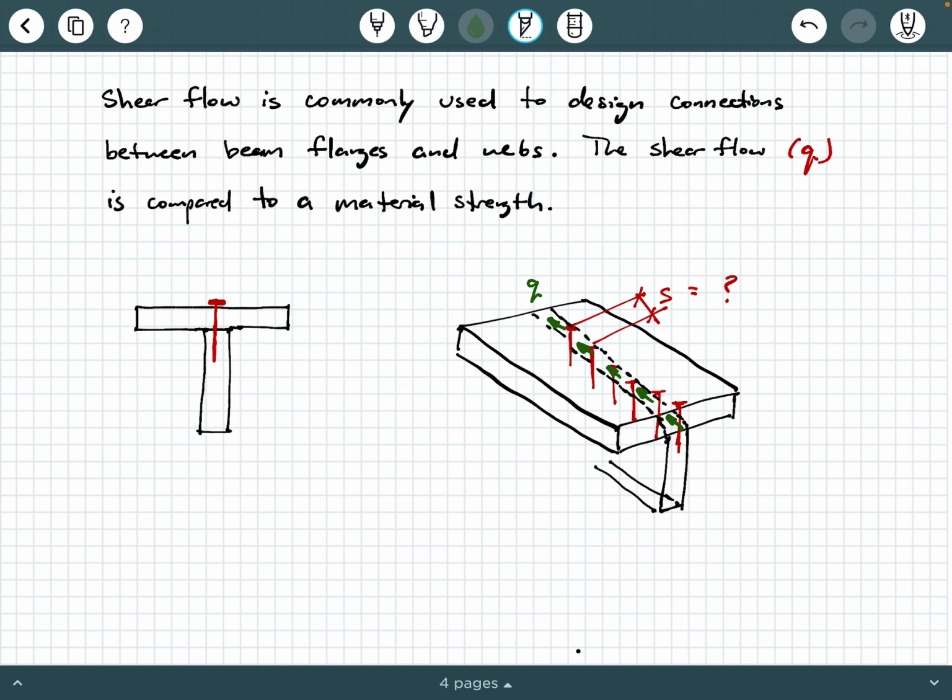What if you wanted to weld two steel members together, right? What if you don't have wood? What if you have some kind of metal like steel? Okay, and you need to figure out what kind of welding pattern you need to use. Well, you calculate q, VQ over I, V capital Q over I, and then you compare that to a weld strength, and that'll inform you on what kind of weld pattern or what kind of weld thickness you need. Okay? So that's why we are concerned with little q. Again, it's to connect elements together for the purposes of a built-up beam.